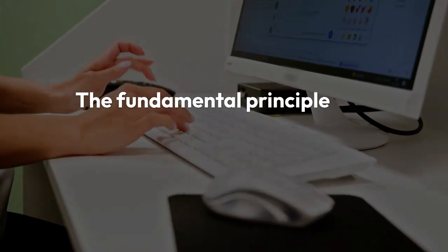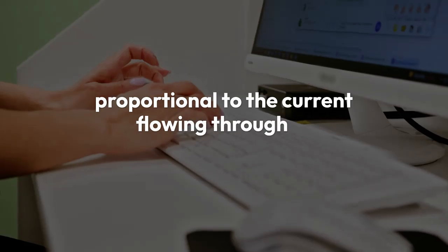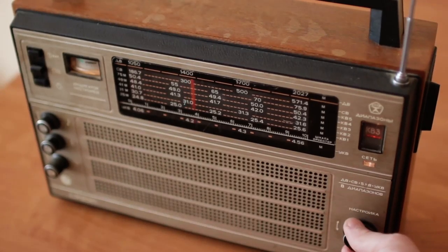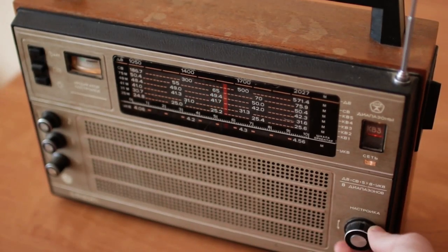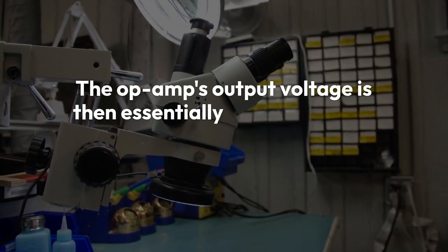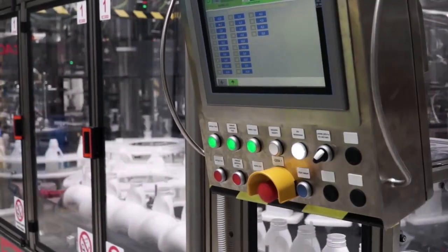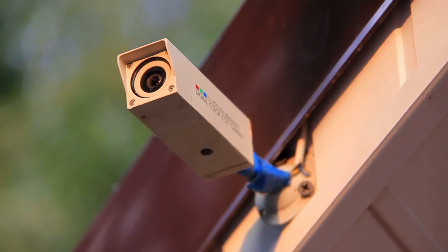The fundamental principle of a capacitor is that the rate of change of voltage across it is proportional to the current flowing through it. In other words, the voltage across the capacitor is the integral of the current. Since the current flowing into the capacitor is determined by the input voltage across the resistor, V_IN/R_IN, the voltage across the capacitor becomes the integral of the input voltage. The op-amp's output voltage is then essentially the negative of the voltage across the feedback capacitor due to the inverting configuration. Therefore, the output voltage is directly proportional to the integral of the input voltage.